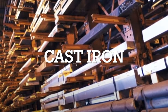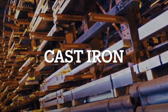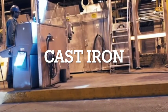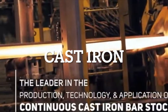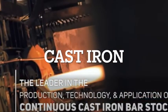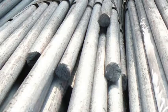A hard, brittle, non-malleable iron-based alloy containing 2.0% to 4.5% carbon and 0.5% to 3% silicon, cast in a sand mold and machined to make building products. Malleable cast iron. Cast iron that has been annealed by transforming the carbon content into graphite and removing it completely.